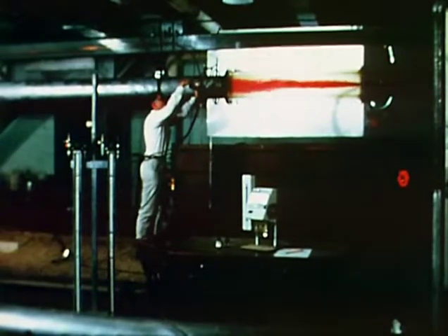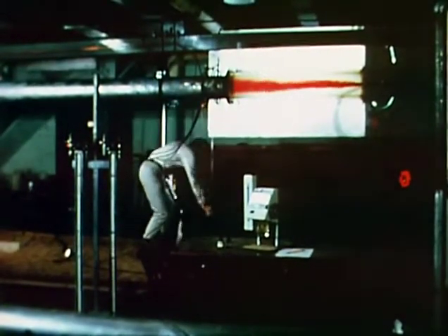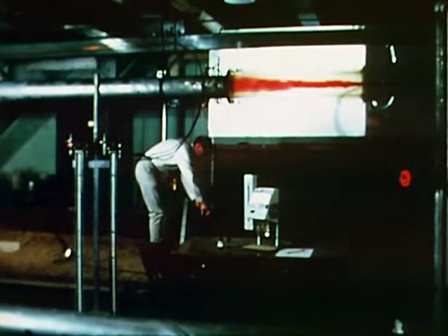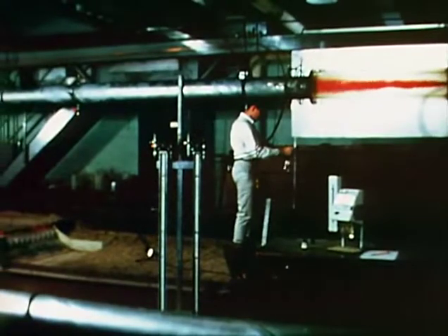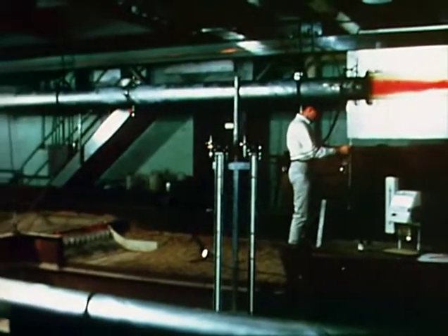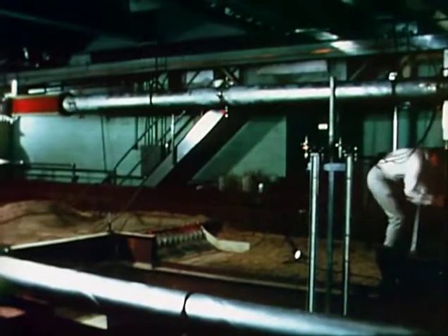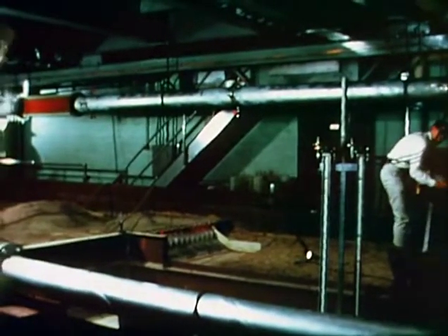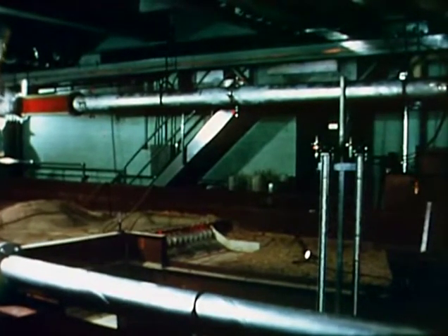Experiments have been conducted in a 200 feet long, 10-inch diameter pipeline to measure turbulent dispersion of chlorine solution injected near the wall of the pipe. The pipeline is arranged with a 120 pipe diameter inlet length to assure fully developed turbulent flow, and is provided with discharge measuring equipment, pressure measuring taps, and concentration sampling devices.